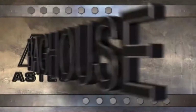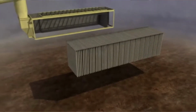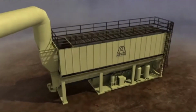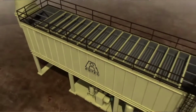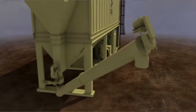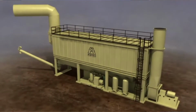So we're going to look at this animation of the baghouse. I'll try to narrate the dust coming through the system. Here's the tube sheet with all of your bags. According to capacity and CFM, the bag count will change. You will have to have extra modules for the larger capacity plants or if you're in higher elevation. This is the solenoids. This is actually where it's a pulse jet, so that means the plant air compressor is providing that air to shock those bags or to knock the dust off the bags. Here's your screw conveyor to convey it to the drum. And then as you see here, here's the exhaust fan that pulls up to the back side of the baghouse.